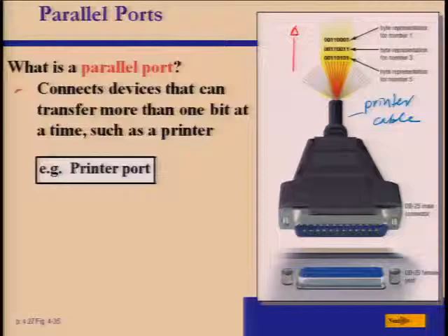The opposite of the serial communication is parallel. So we have a parallel port also in most desktop computers, in the PC. In the notebook, I don't think it exists anymore. There are no more parallel ports. Okay, what is a parallel port? It connects the external device and sends data not bit by bit. This time it will be byte by byte, at least, right? 8 bits. It said more than 1 bit, but normally people don't send 2 bits and consider it parallel, right? They will send out a whole byte, okay? So 8 bits at one time in this case.